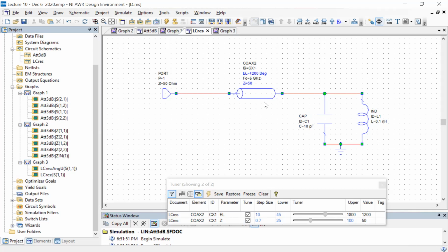You could, if you had a model, probably do this, but in most cases you won't really know what's going on with this object. And if there is too much going on with this object, even the calibration procedure won't work very well. Okay, we will see later on what kind of things can be calibrated out. So this was about just a section of transmission line and then mismatches, which give rise to additional resonances. And these are all very common things which happen, not as exaggerated as what I showed you, but it happens in real setups and one needs to know how to deal with it.